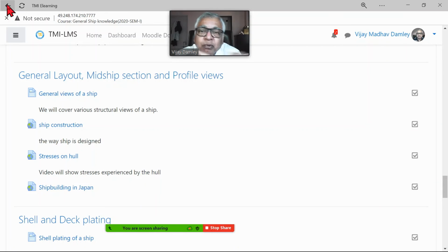We have a lot more lightening holes, because by reducing that much weight, you take the percentage. Suppose everything is solid, no holes anywhere, and we created a ship. Assume the weight is say 1,000 metric tons, and now I take another ship and I start cutting holes without reducing the strength. It is possible, according to physics and metallurgy, to cut holes to make it lighter.